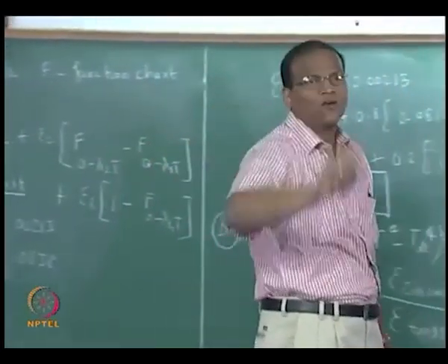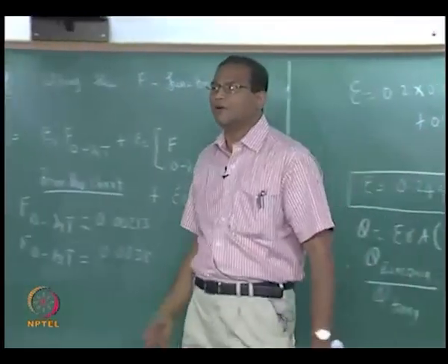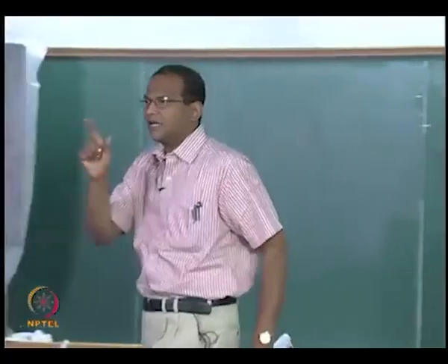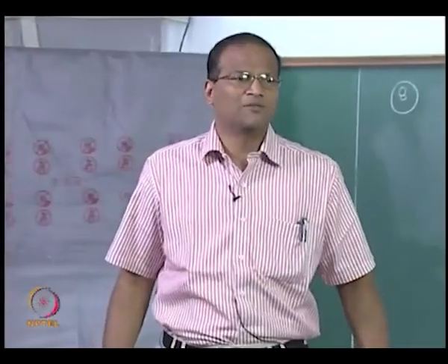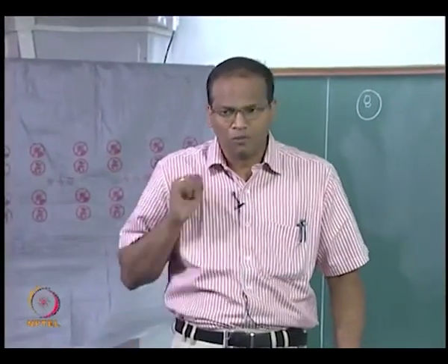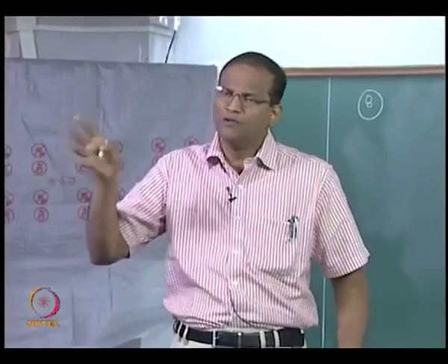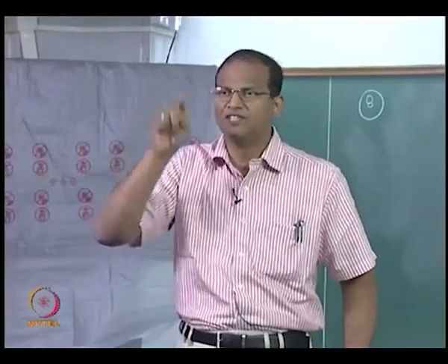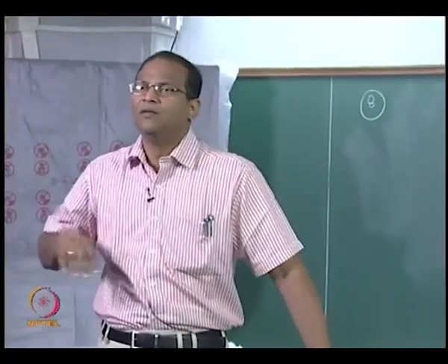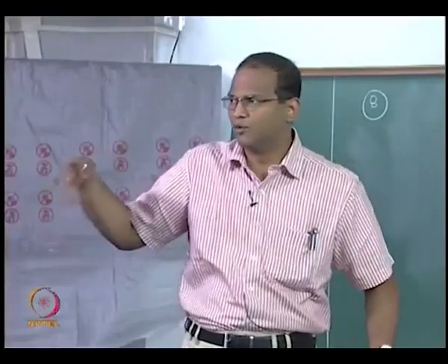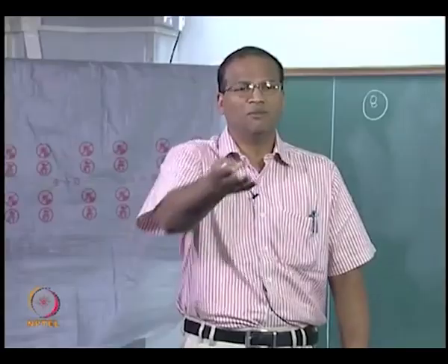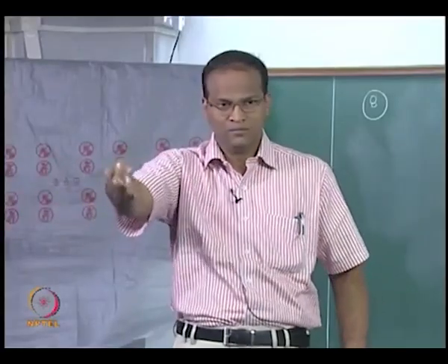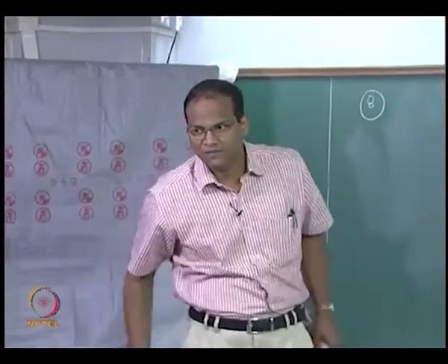The radiation which is coming out of the bulb must be equal to sigma T to the power of 4 into the black body fraction corresponding to the 0.4 to 0.7 micrometer band, multiplied by the corresponding emissivity. This we can work out for both the bulbs. If you want, you can substitute the value for sigma and T and put it as a number. I would much rather keep it as sigma T to the power of 4 because I am looking only at the ratio. Then I will be finally convinced that the zirconia bulb is far more efficient. Okay, just work it out.